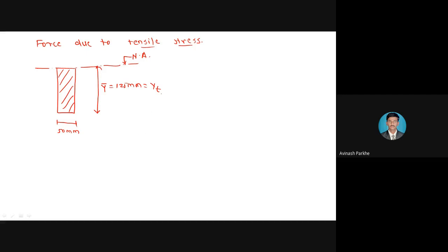Okay, so we are having the formula. Tensile force is equal to average tensile stress, this is very important, into area under the tensile region.